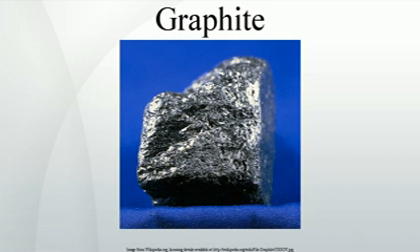Graphite and graphite powder are valued in industrial applications for their self-lubricating and dry lubricating properties. There is a common belief that graphite's lubricating properties are solely due to the loose interlamellar coupling between sheets in the structure. However, it has been shown that in a vacuum environment, such as in technologies for use in space, graphite is a very poor lubricant.